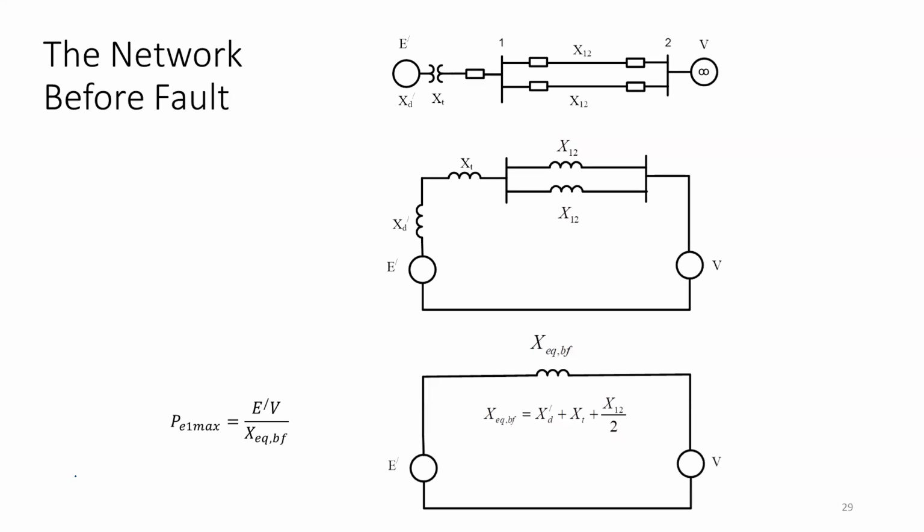So what will be the change? Sir, X12, the line that was shorted, will no longer be in account. Why? Sir, due to the short, it will be flipped off. I'm talking about after fault. During the fault, it will be shorted. That is fine. But what will happen after fault?